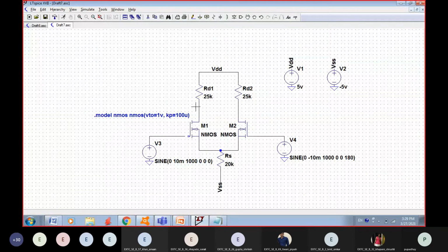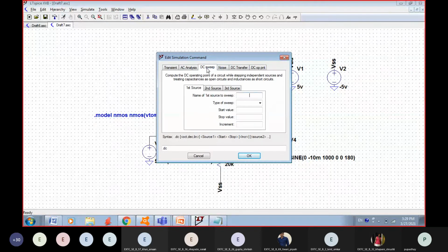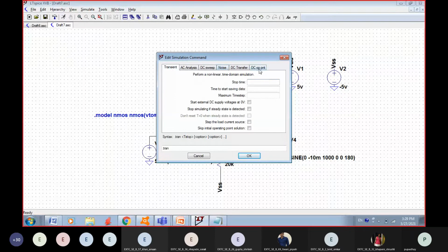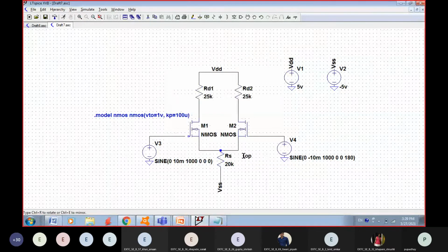We can just go and click it, and everything is just a click away. So anybody remember what we do? We do a command. There are a lot, like we have seen, a DC, AC analysis, a transient analysis. But now we will be going for DC output at this point. So this OP command will be going for, and then we will place it here. Now when we simulate run, whatever may be the error, the error will be popped up.